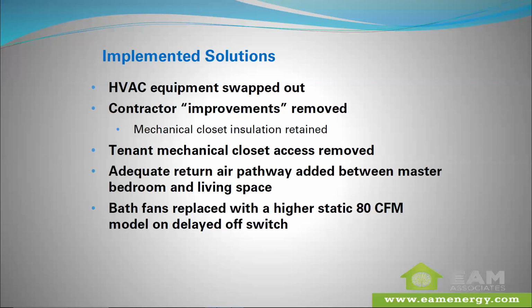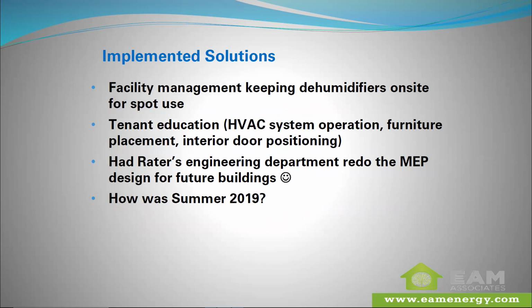And then the bath fans were replaced with units that had a higher static capacity, and we added the delayed off switch to rectify that. The facility management was also keeping dehumidifiers on site for some spot use where it was needed. Kind of like what Michael talked about, we did some tenant education on the system operation: placing furniture so it doesn't block transfer grills, supply air grills, and return air grills, and leaving interior doors open as much as possible, only closing them when privacy is needed.